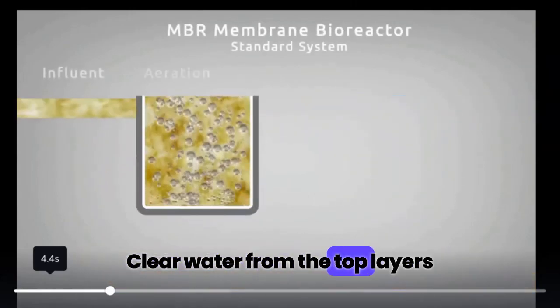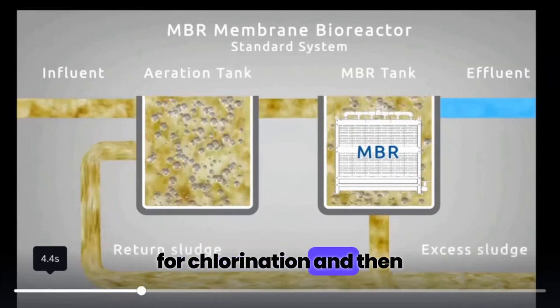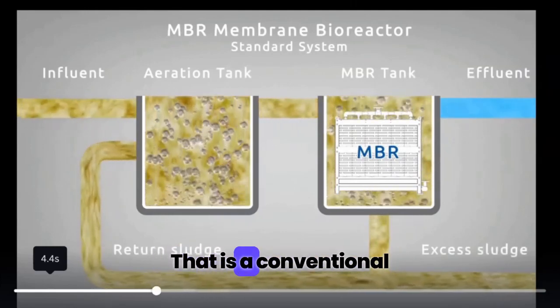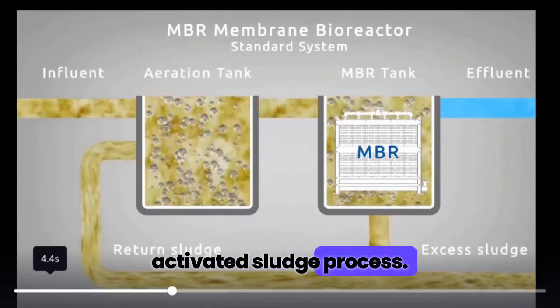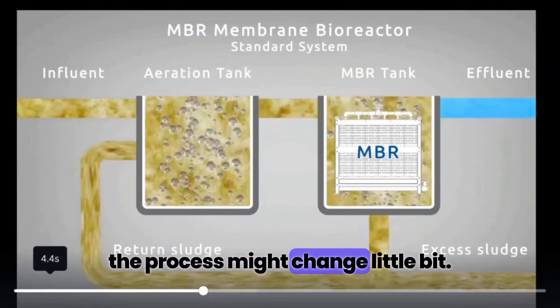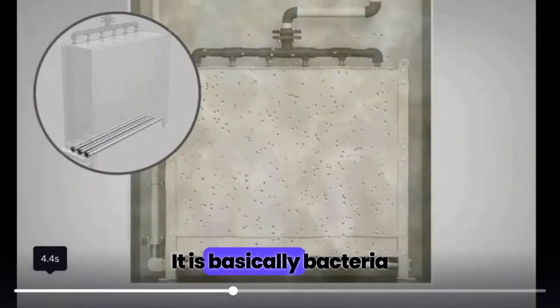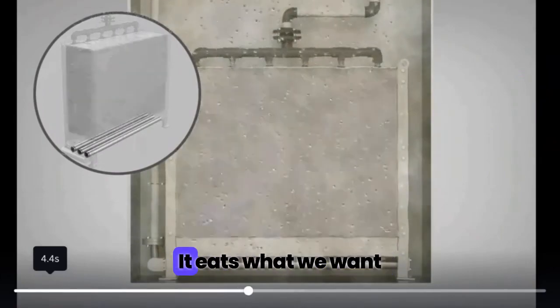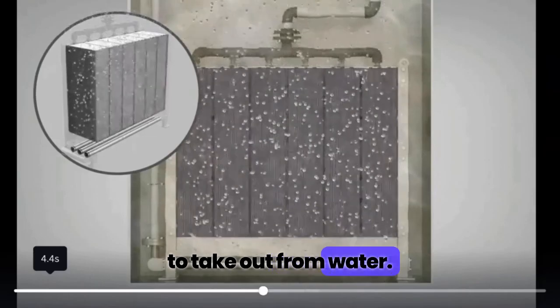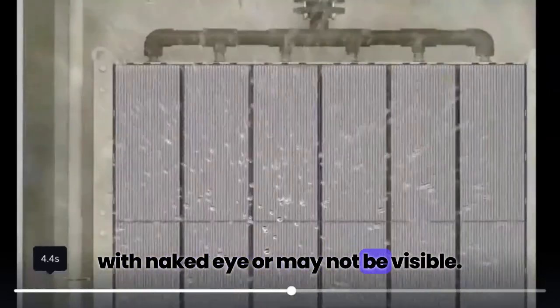Clear water from the top layers of the settling tank goes for sand chlorination, and then sand filter, carbon filter. That is a conventional activated sludge process. Whether it is MBBR or SBR, the process might change a little bit, but otherwise the underlying principle is the same. It is basically bacteria that you are growing, and it eats what we want to take out from water. That particle may be visible to us with the naked eye or may not be visible.